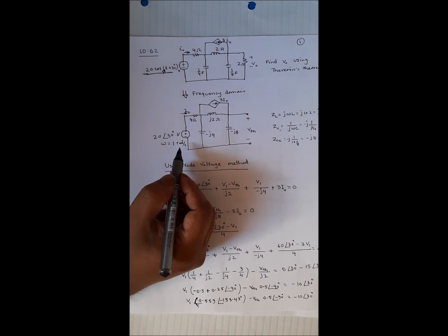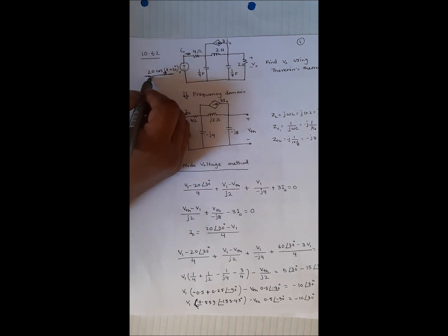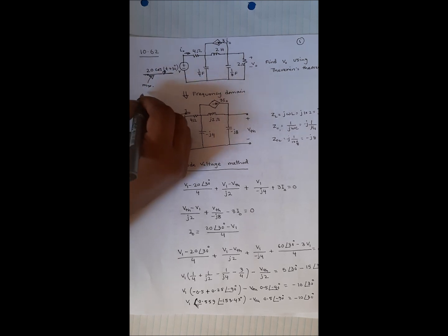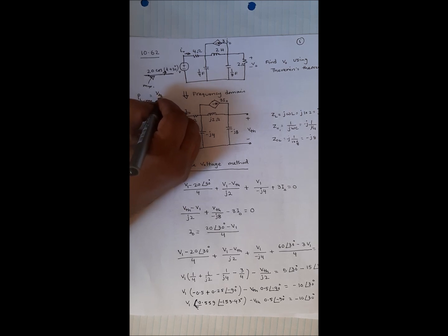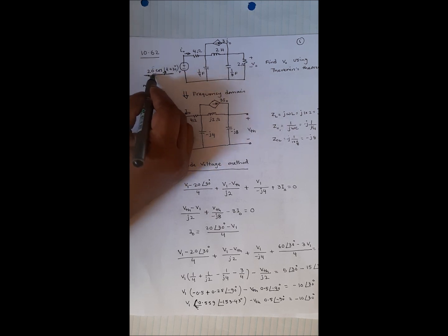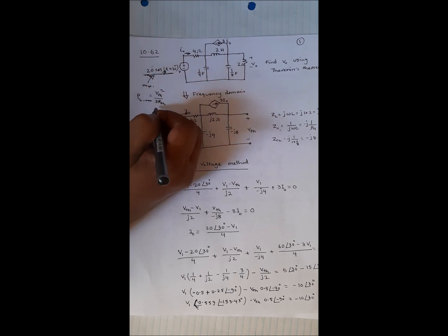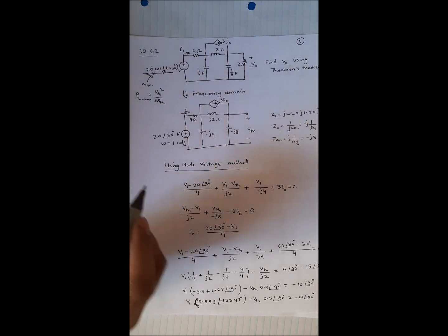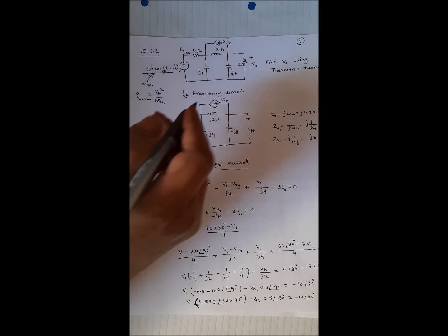So here you see the equation is given in terms of maximum value. So if someone wanted to find PL max, the formula will be B Thevenin squared over 8 R Thevenin. Because it is given 20, not in RMS, it is in the maximum value, so the formula will be 8 R Thevenin. Okay, that's another thing.